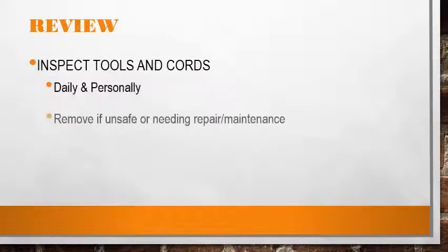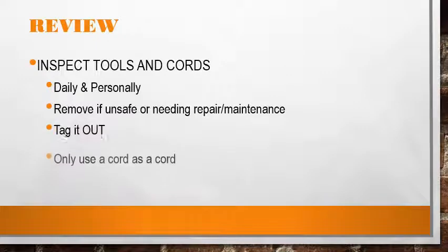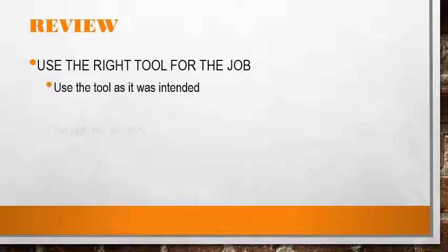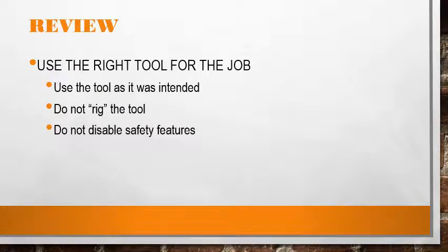Inspect all tools and cords daily and personally. Remove tools that are unsafe or needing repair or maintenance. Tag them out, and only use an extension cord as an extension cord. Only use tools that you are properly trained in. Use the right tool for the job. Use the tool as it was intended.